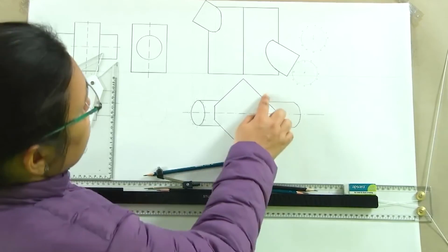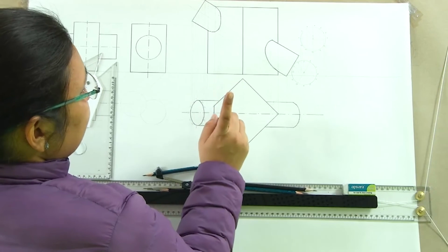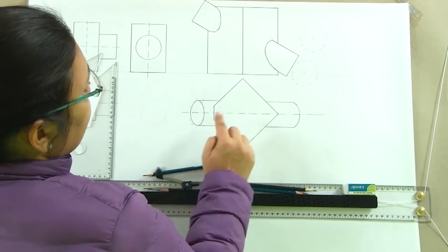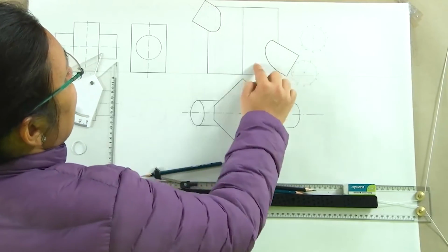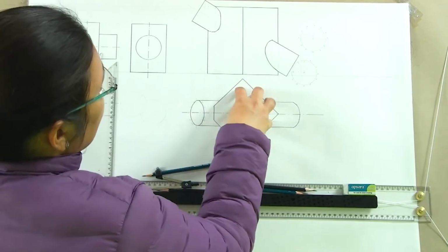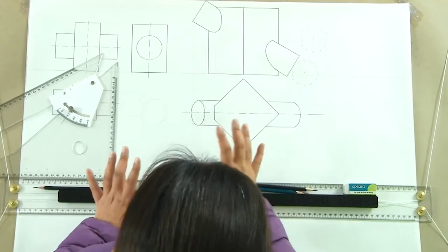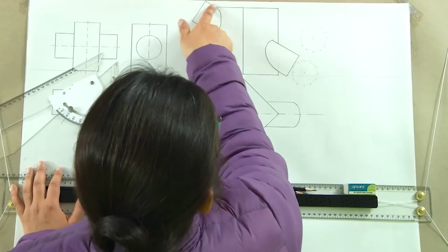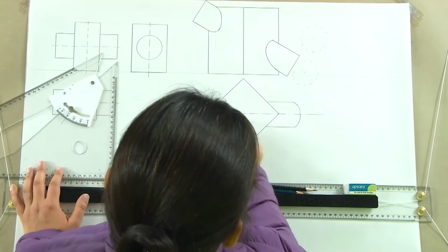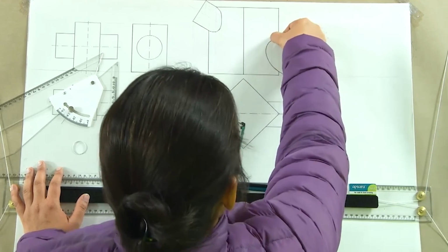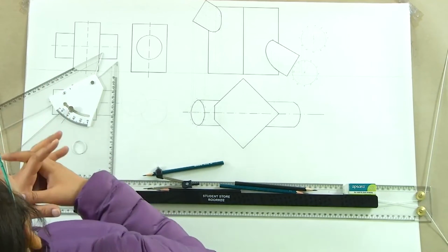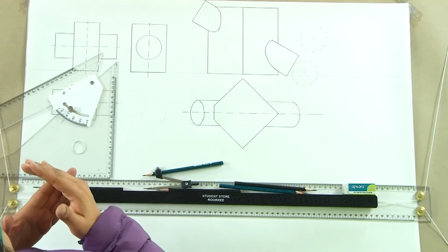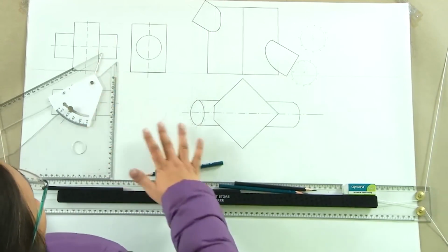This is what we are doing and getting the projections in place for any solid for that matter. If it was a circular solid, so instead of a square prism, if we had a circular cylinder, in that case what we would also have is, instead of these 4 edges which are here, we would have again these 12 points, and wherever the generators of both will intersect would have determined how these cylinders are going to intersect. That is how we would have done in case this was a cylinder. Either way, what we have to keep in mind is that if the projector of 4 is here, it has to match with the projector of 4 horizontally. The projectors, whether they are coming from the vertical plane or the horizontal plane, will result in a point only when they intersect. So, keeping this fundamental in mind, this is how we would draw intersection of surfaces.